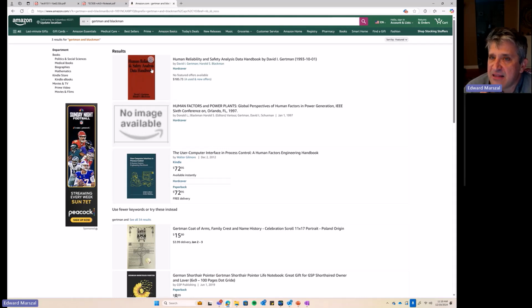And that's the key concept that we're going for in functional safety assessments, in audits, in commissioning. So the probability of an installation error being detected during commissioning is actually relatively high, because you've got an independent third person who wasn't involved in the installation checking it out.